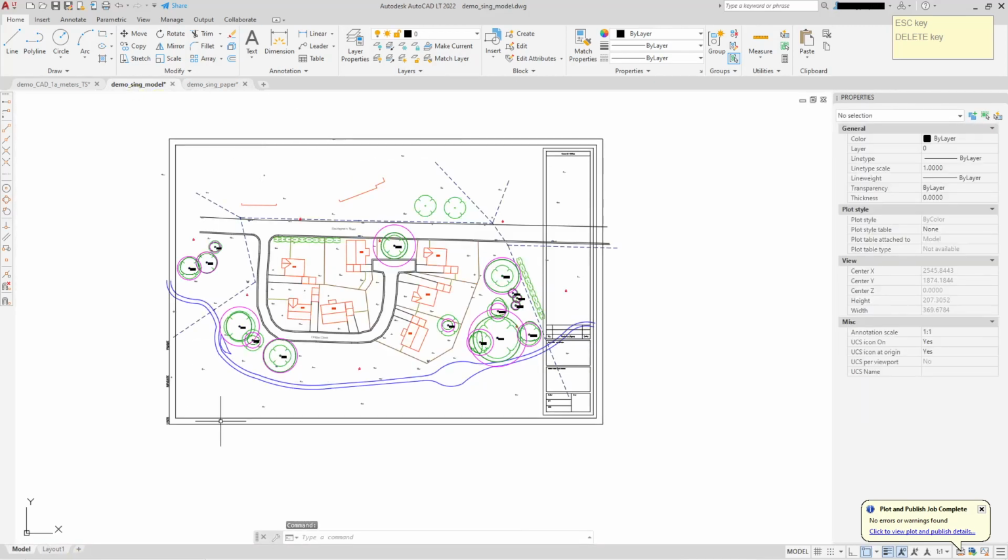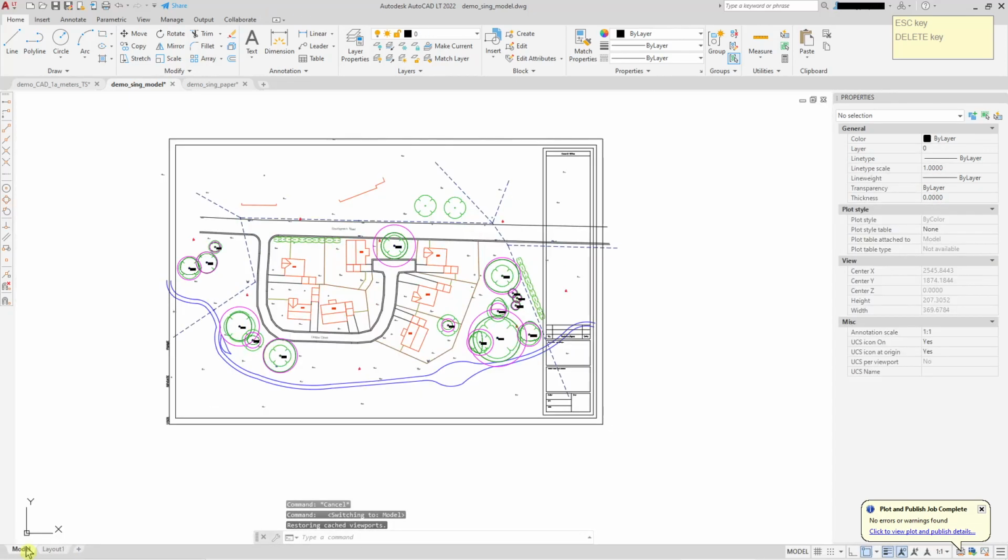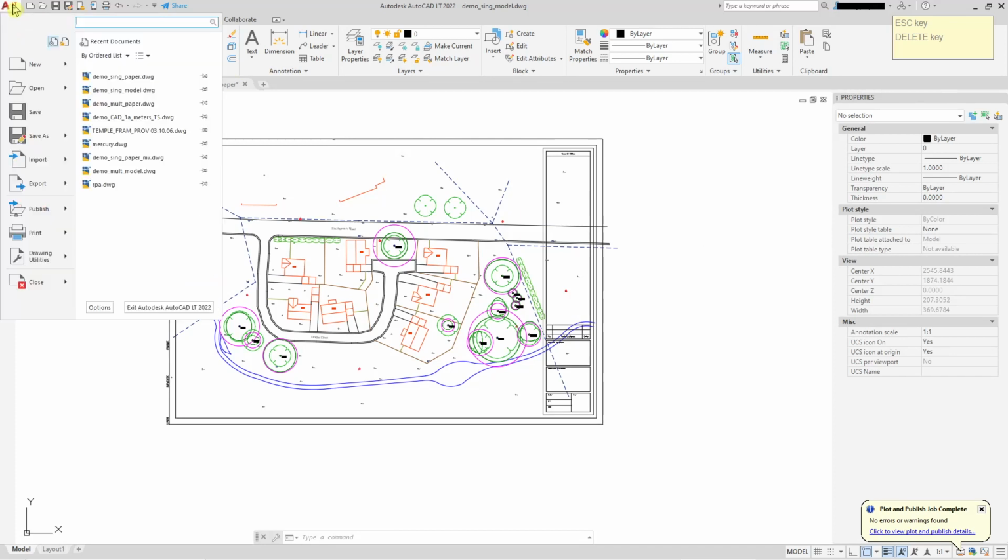Well, of course you can't import it from here. You could have all this as a block, I guess, and put a block and stick it on model space. But again, you've got all these extra problems with it, so you should always use paperspace for layouts. And the problems increase when you need to do multiple sheets. If you've got a big site and you need to have lots of sheets to cover it, and use model space for your templates, then the problems increase.